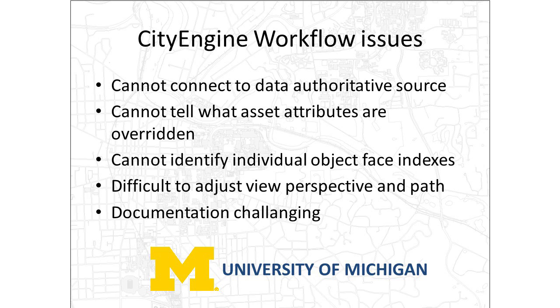In that when you are reading your attributes from a file geodatabase or a shapefile, you have the capability of overriding what any of those values are for any individual object. So imagine you've got 4,500 light poles, and you're working with one and trying to tweak it in, and you've done some overriding with that. You can't close it and come back later and find out what's overridden without looking at all of them. So it's an area that they need to improve on.